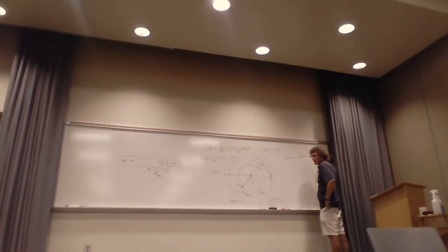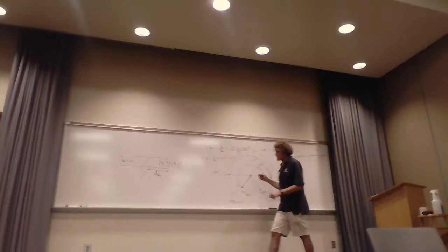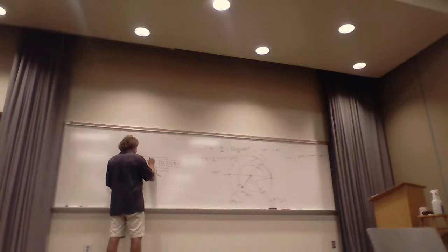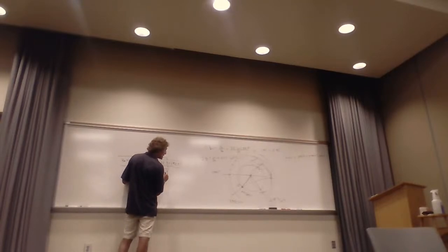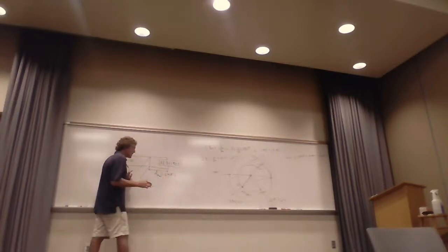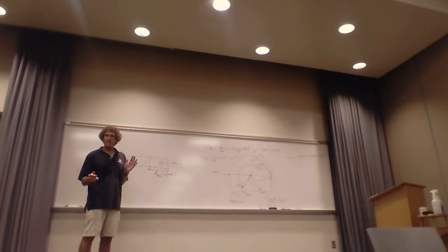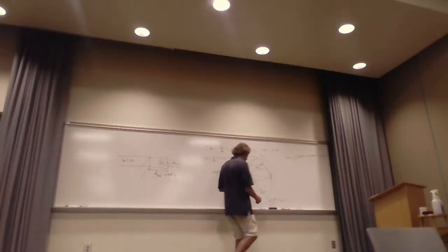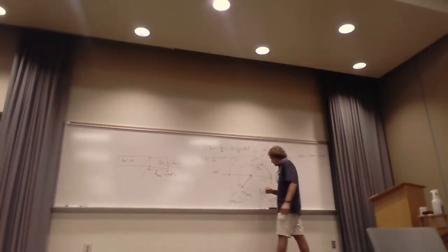0.405, did you say? Yeah. Yes. So that's to this point right here. This D through where you attach right here would be 0.405 lambda. Now we've got to find the stub length, right? So we need the stub. If we went down to here, this is minus j0.8, right?